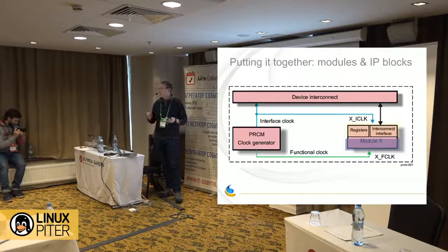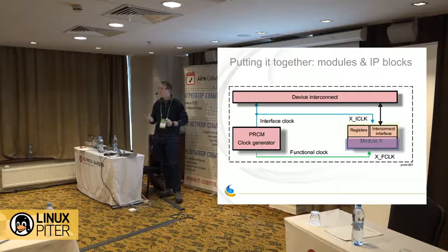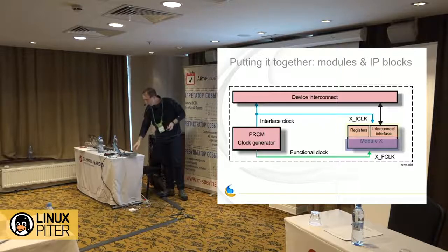Gating either of these clocks will obviously impact the functionality of the module. It may turn the module off, or it may only turn off a part of the module. But it will also save power. Clock gating is one of the most fundamental things that we have in terms of trying to do some basic power savings. A lot of times in chips, in fact, if the only thing you do is enable clock gating for the whole platform, that's where you'll get like 80% of your power savings. That's the 80-20 Pareto principle. So this is the lowest level thing that we can do: just clock gating on modules when we don't need them to be functional.